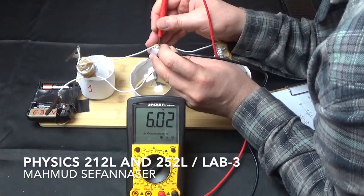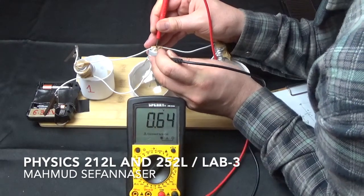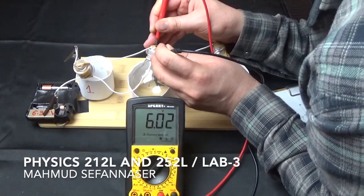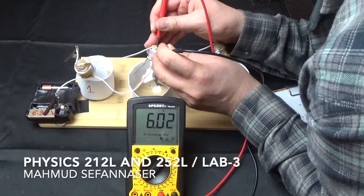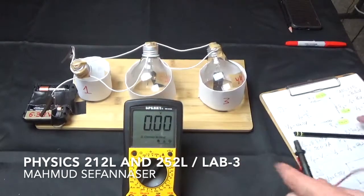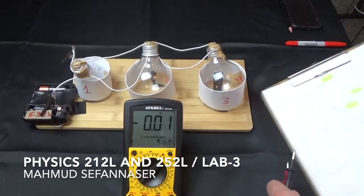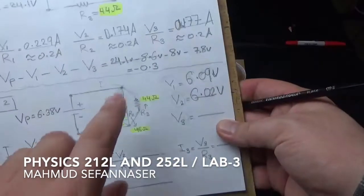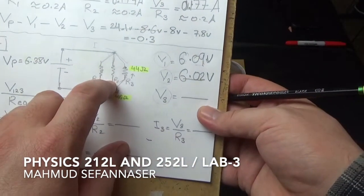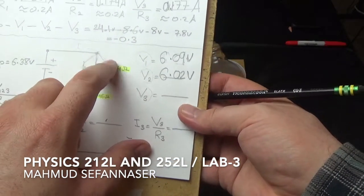So we have 6.03, 6.02. We have 6.02. Okay. So V2 is equal to 6.02 volt. So this is the voltage across resistance number 2. Let's now move to number 3 and measure the voltage here and see what we have.